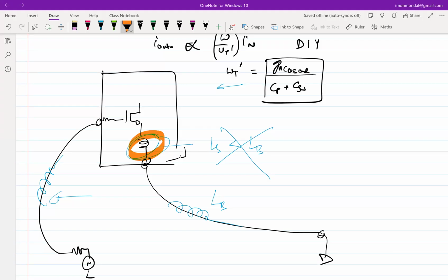It comes with the resistance of the Ls, which means there will be a DC voltage drop across the inductor, which means the effective gm is also going to go down. And not only that, you are going to get additional noise because of the Ls. So the moment you have on-chip inductances, you have to take care of the noise. If you have off-chip inductances, their quality factors are very good compared to the on-chip inductances, by a factor of 3, 4 at least. So in that case, you have to take the existence of them into account.